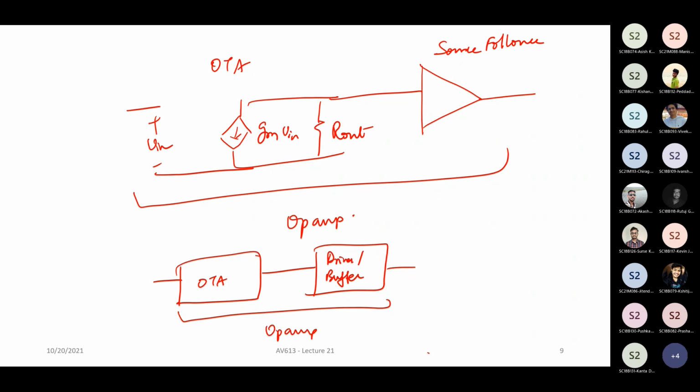In many of our analog VLSI or mixed signal chips and analog ICs, most of the time you are not driving any resistive loads. That is thanks to the way the MOSFET device is. At low frequencies, the input impedance of any transistor is only capacitive. You do not have a resistive component at low frequencies.